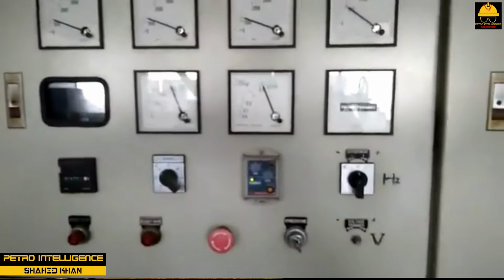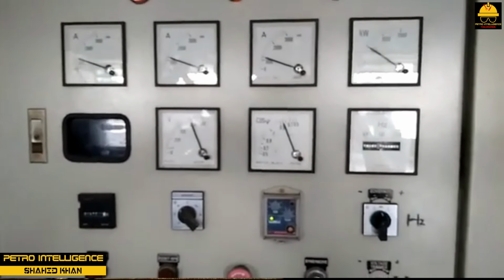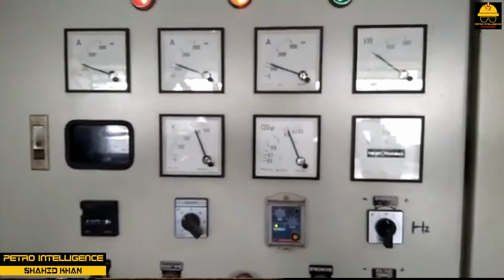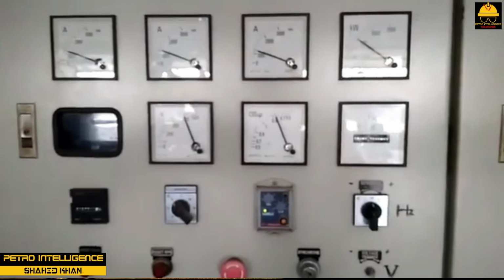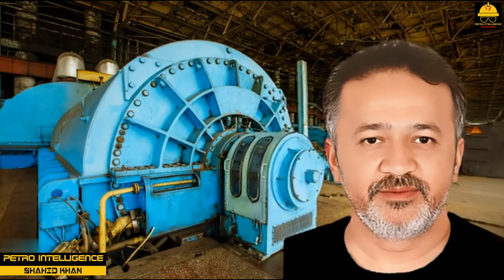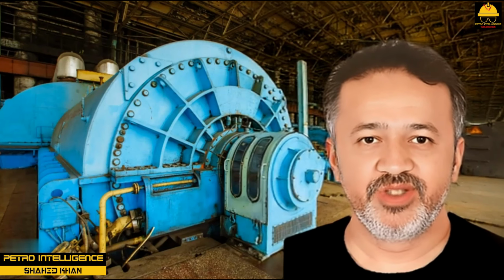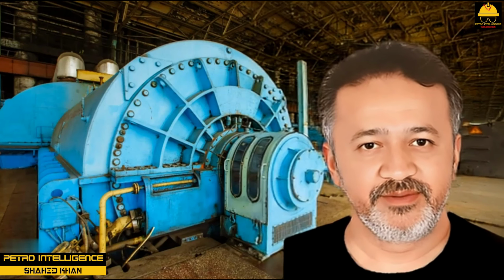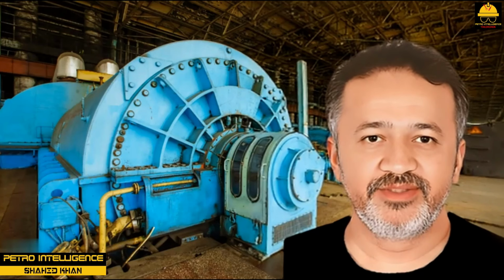As discussed earlier, the governor system is responsible for the speed the turbine operates. Occasionally, the mechanical linkage between the governor and governor valve will bind. This binding causes the steam turbine to hunt. Sticking or binding problems can be resolved by lubricating the linkage on the steam turbine. Inlet steam pressure problems can also cause a steam turbine to hunt.